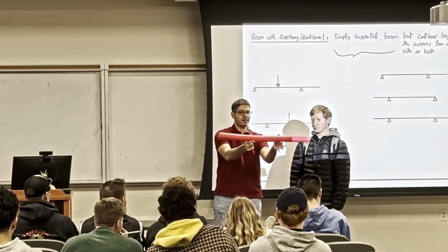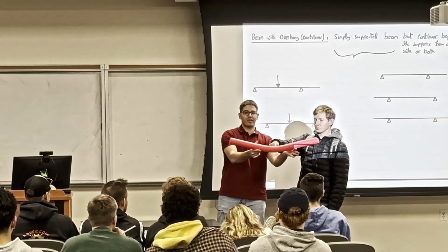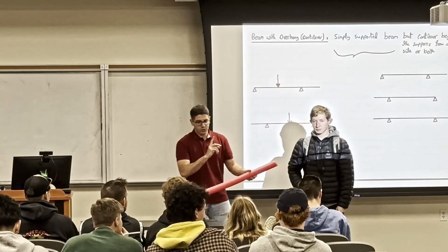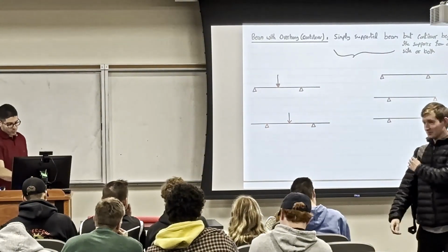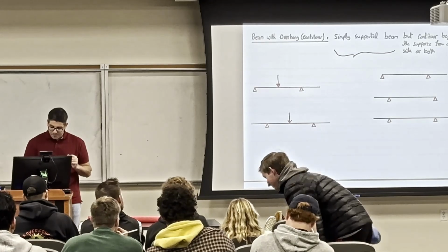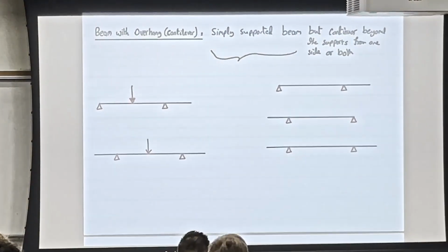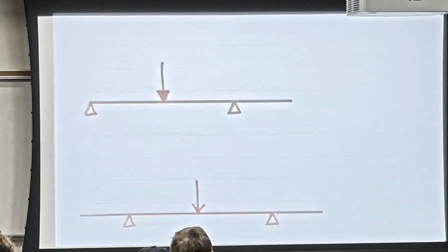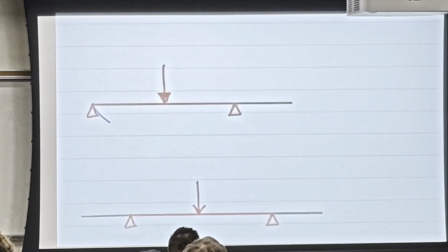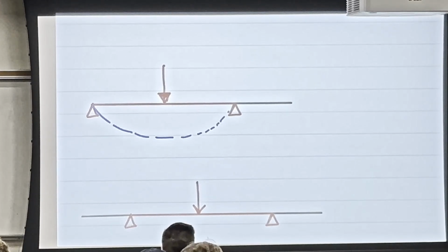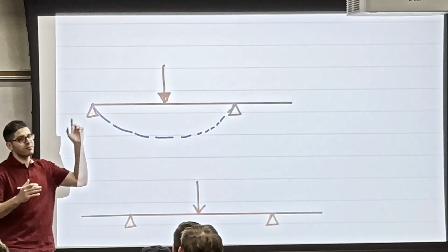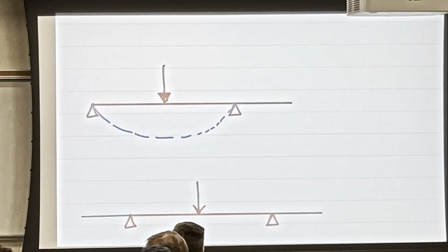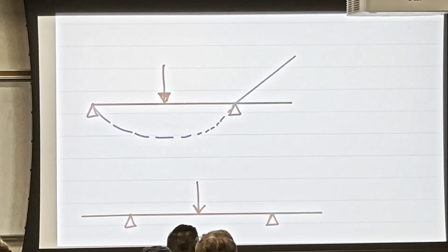What about beam with double cantilever? Put your load in the middle. What happened at the both ends? It goes up. So with this, thank you. With this, what I'm proposing is, for the middle part, you're going to use the table. So we know from the table, as I'm sure that you know how to use the table now. And whatever extended from the beam, you're just going to extend a straight line, like this, with the same slope that the curve ended with, okay?